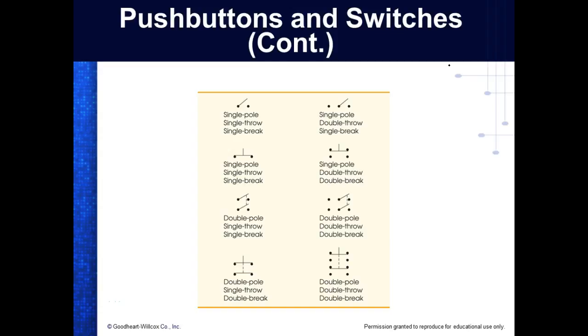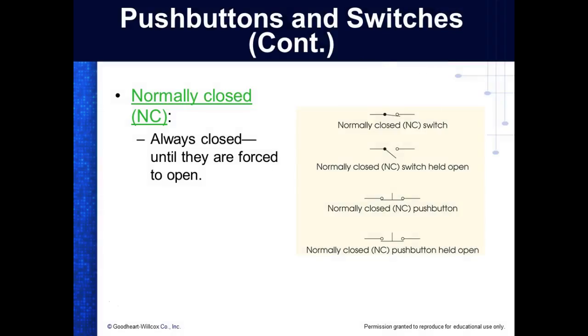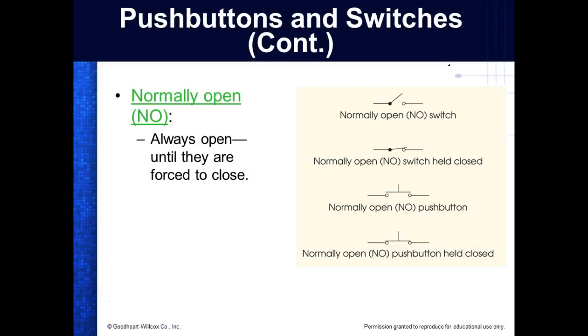I was looking here, I was also kind of going along with the lab. And I noticed that every time you got a closed switch compared to an open switch, they usually put the line of the switch on the opposite side of the contact. Not on toggle switches. On toggle switches, whether it's normally open or normally closed, we still put it on the top. But notice what they do on the toggle switch. You normally open, rest up above it, you normally close above here and rest on the little terminal. These are for switches.